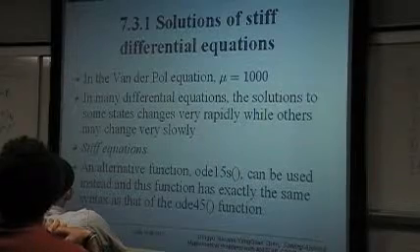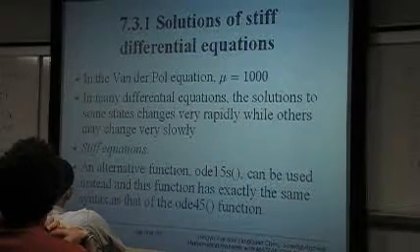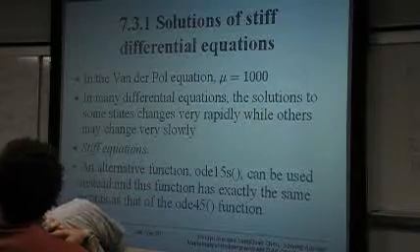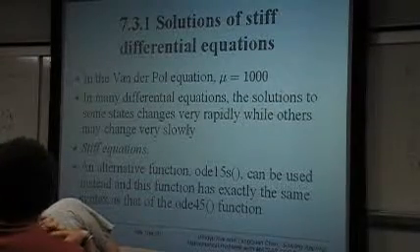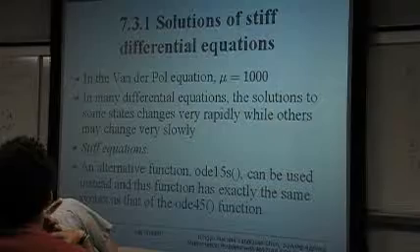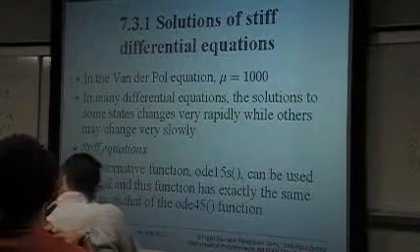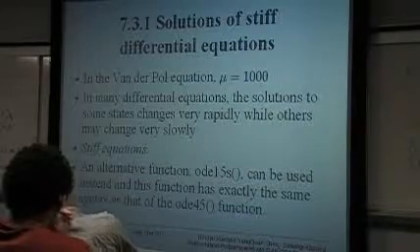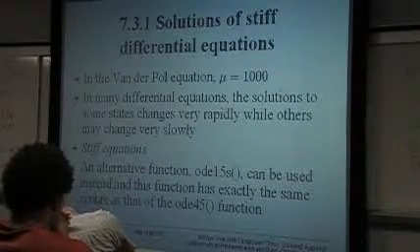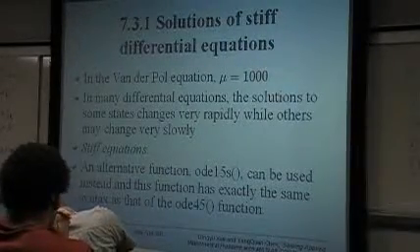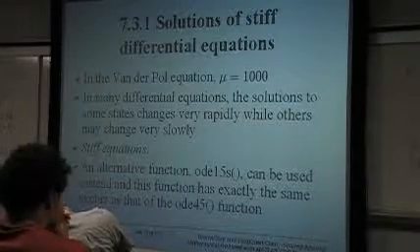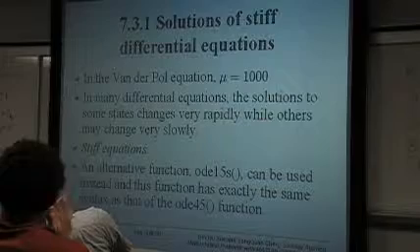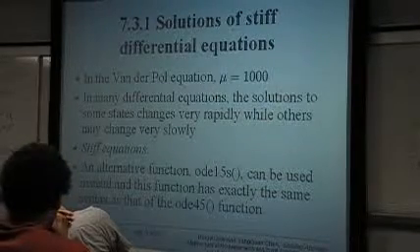And here, 1,5 means the order of the solver changes automatically between 1 and 5. The order will change automatically according to the solution itself. So sometimes it may use a first order approximation, that is the Euler method.